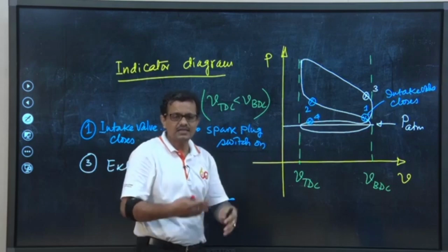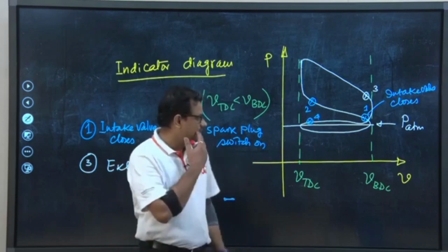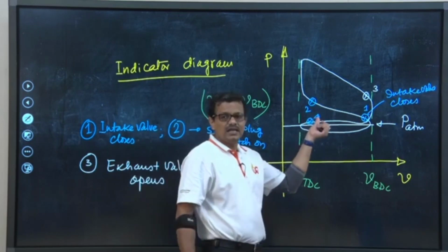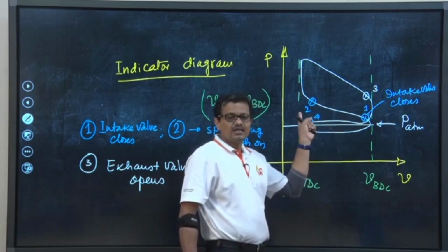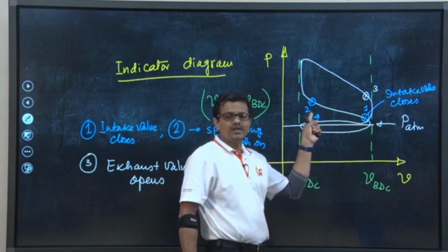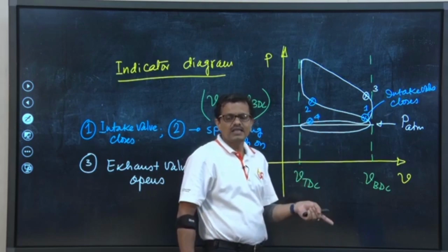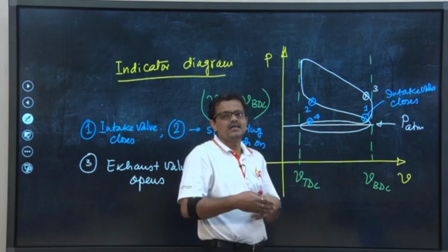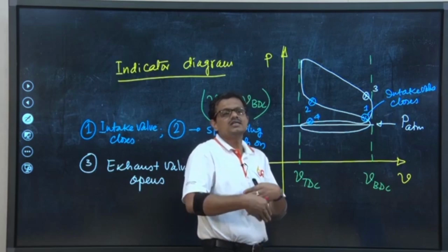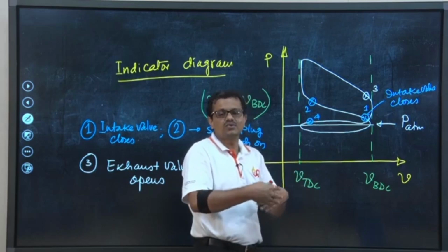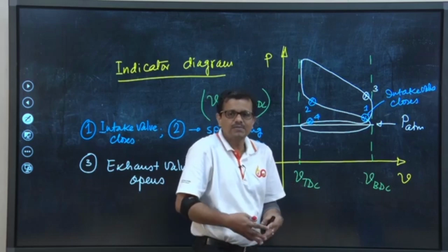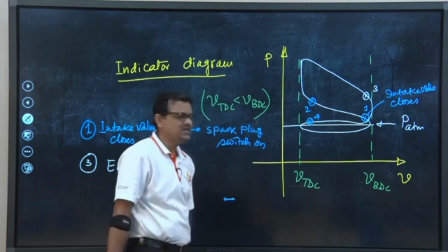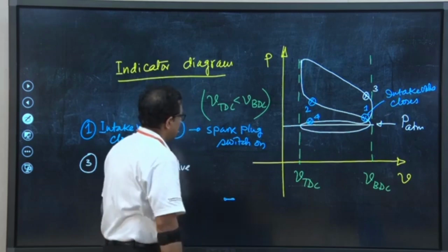Again there is a logic behind it, because if we open the intake valve, exhaust valve is remaining open, the opening intake valve will allow fresh charge to come in, and that fresh charge will allow the exhaust gases to completely remove from the engine cylinder, but it is not even possible to completely remove the exhaust gases.